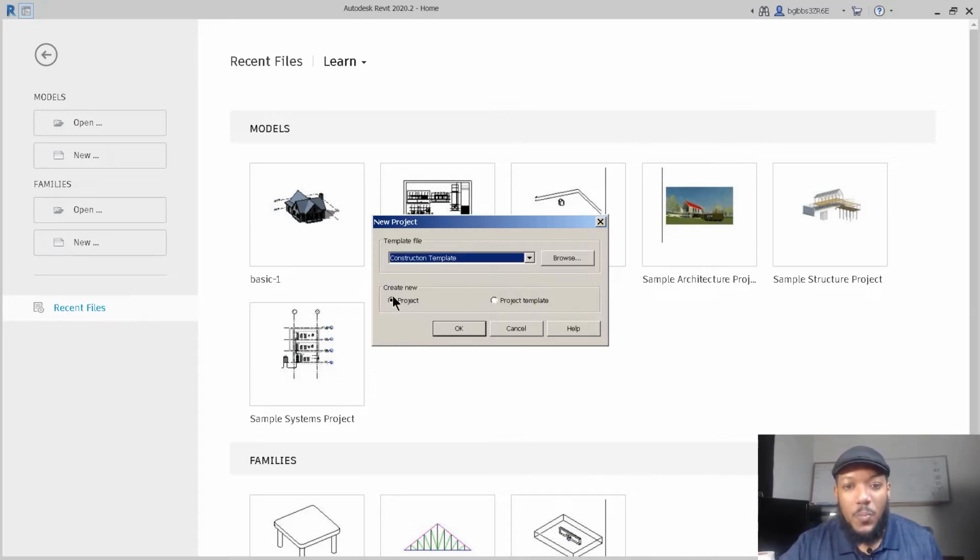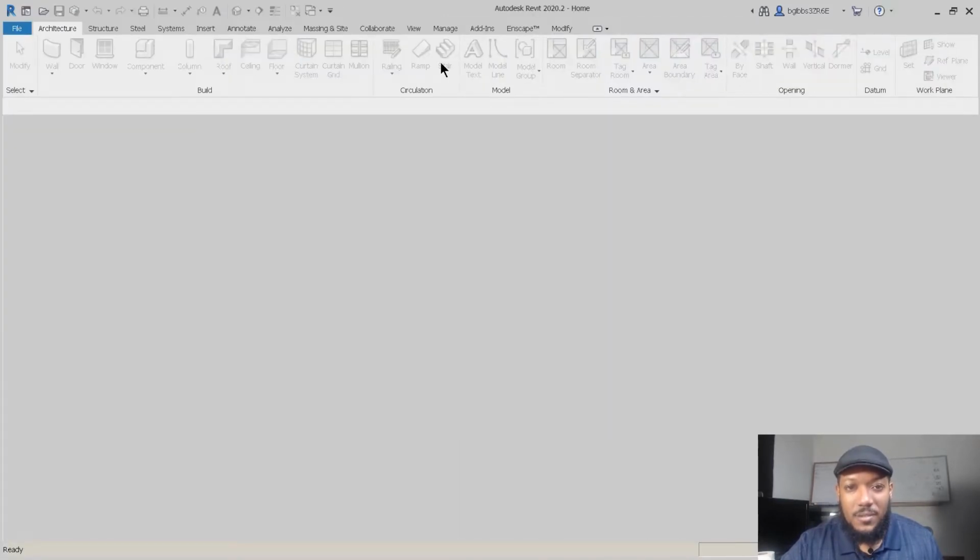And you can also open a project, or you can start a project template. So it's useful to get that workflow, because if you're going to do something again and again, work on a template that you can bring into several projects. That's something that I regularly do, is make sure I'm working from a template that's really properly made. So we're going to open the Revit template for this project, and we'll press OK.